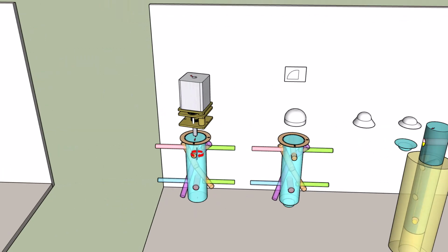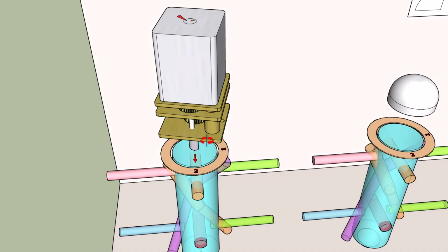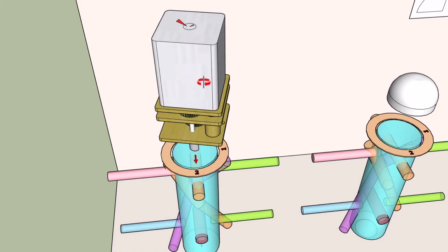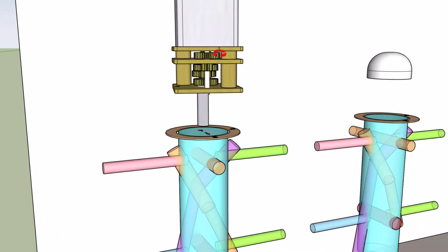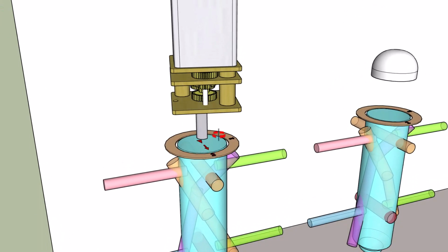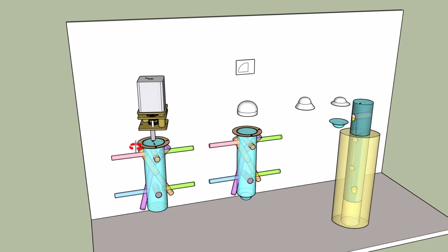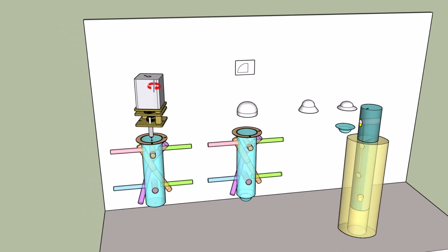And of course, we take a little electric motor, servo motor, digitally controlled with a gear reduction, and that turns this stem. And the effect of this is you now have a digitally controlled valve, and the digitally controlled valve is digitally controlling the extension retraction of the hydraulic cylinders. How about that?